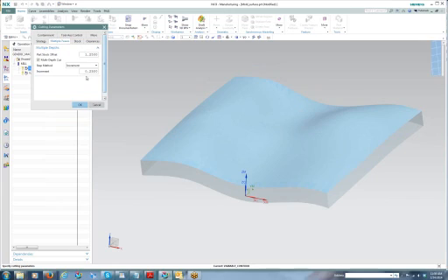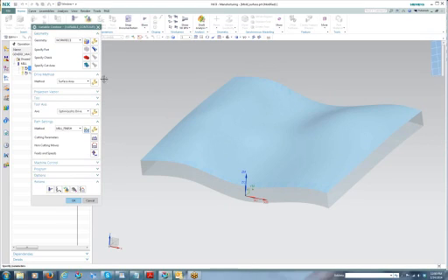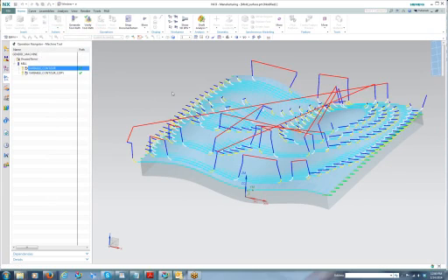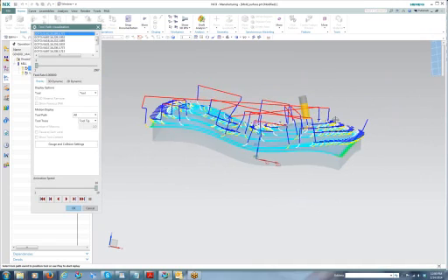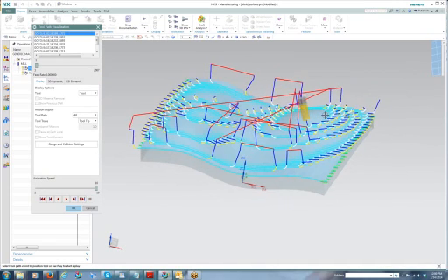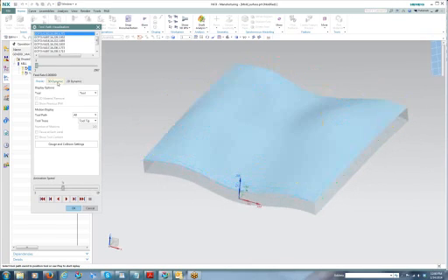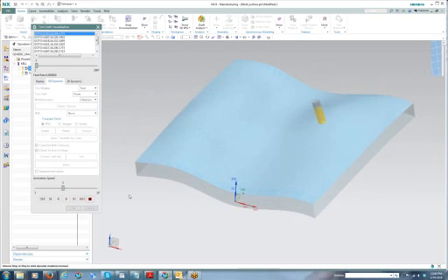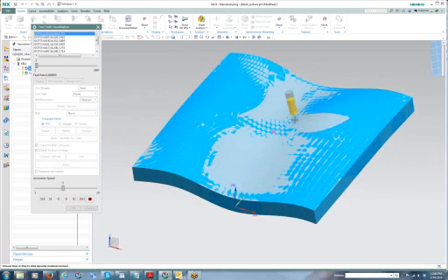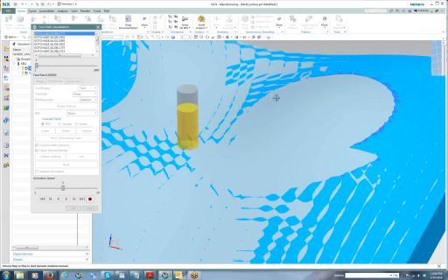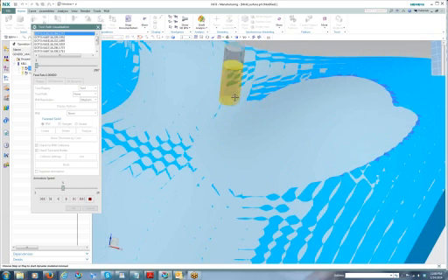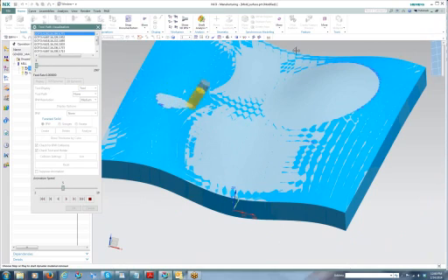We have the multiple passes set here at a depth for each pass of 1/4 of an inch. But because it understands where the IPW, or the in-process workpiece, is, when we actually finish it, you can see that the toolpath puts extra passes in where the two lumps of material are, but not in other areas. Let's quickly look at a 3D dynamic verification of this. So here it's removing this stock in 2 passes, and then you'll see it start to go larger as more and more stock is involved in the cut.